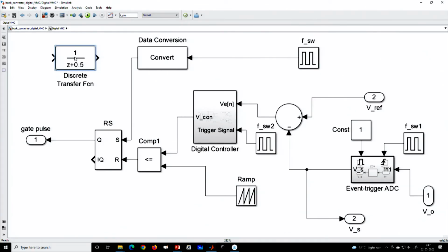We are not going to use the transfer function because we have identified this way of implementation is not going to serve our purpose, because we want to sample with respect to time. You may not want to start sampling at the start of simulation, so we want to customize. Sometimes in digital control we want to speed up the sampling process during transients, so we need an adaptively varying sampling process during runtime. Another requirement may be to use event based sampling. To accommodate all these kinds of customized sampling methods, we should not use any default transfer function block, we should realize it using a difference equation.